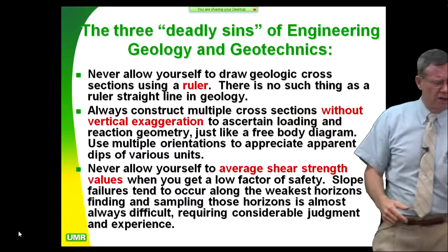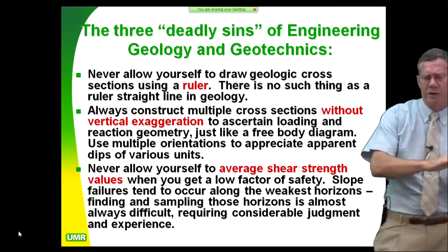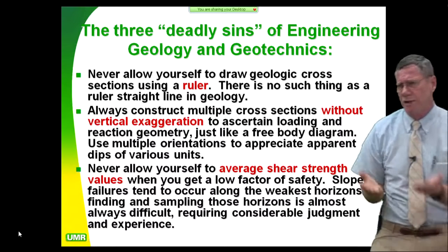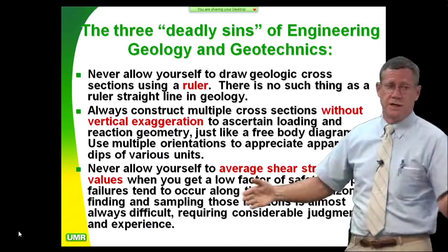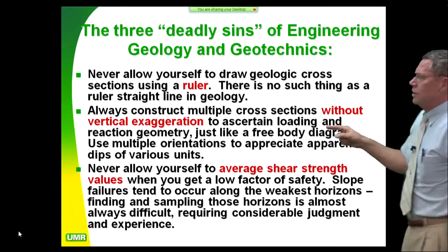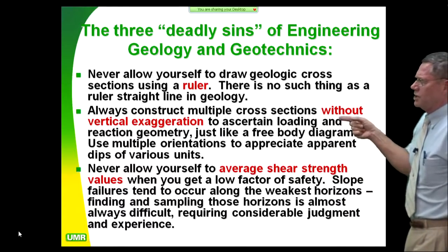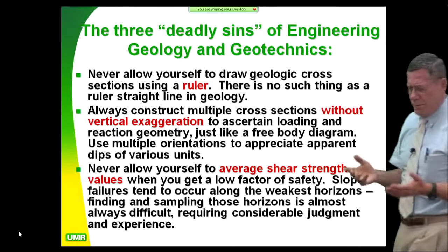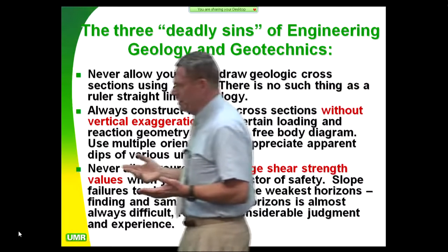Guys that use charts that are assumed, they don't realize it. Those charts were developed for level front fill, level back fill. Then they apply it to a slope situation. They're going to get the wrong answer. Okay, so you're going to have to appreciate the apparent dip of the various units. Apparent dip is incredibly important.